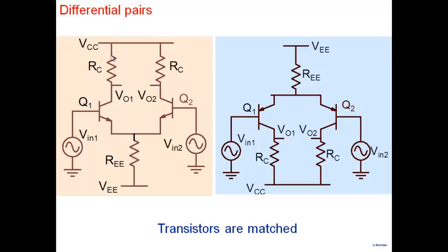So we are starting off with a very simple differential pair with a resistive load that you see here. But with the things that we have already learned, we can very easily now, without requiring, we've already covered the reasons for that. We can replace it by a transistor. We can replace it by two transistors here. We can replace this by a cascode. And you can also see the following. What is the purpose of this REE here? To supply a bias current, right? The REE is there to nothing but to supply a bias current.